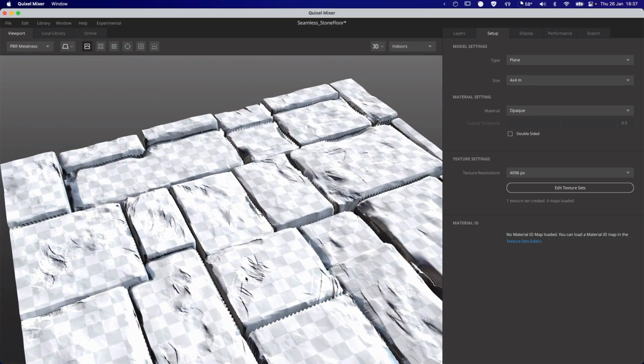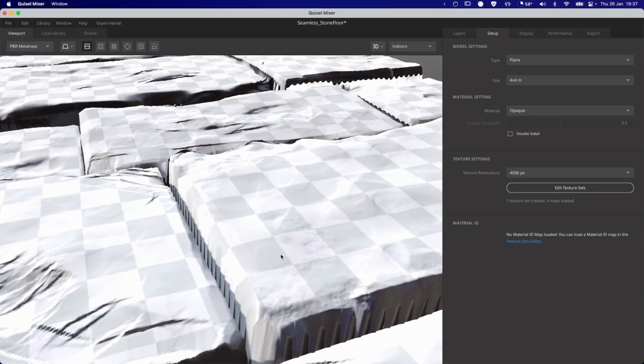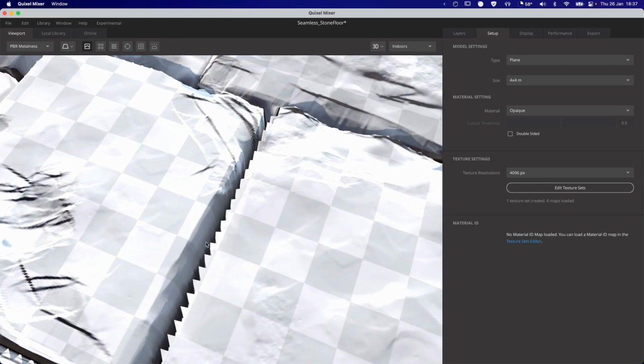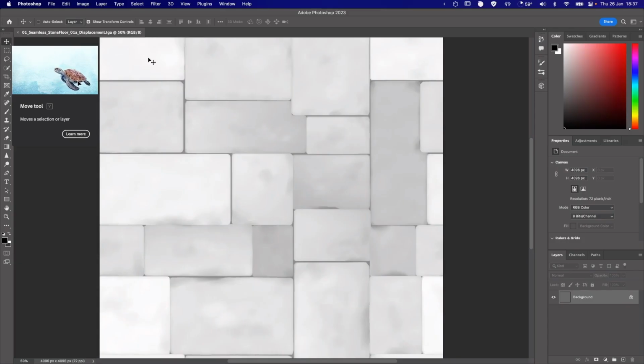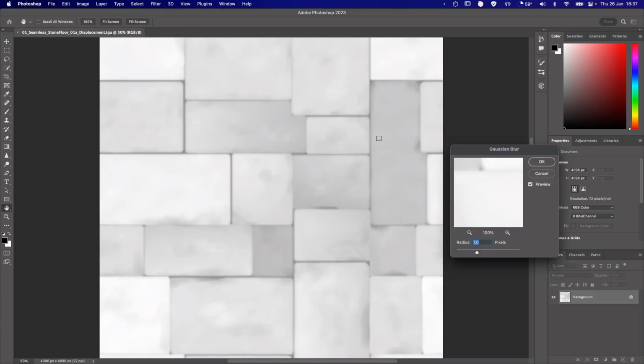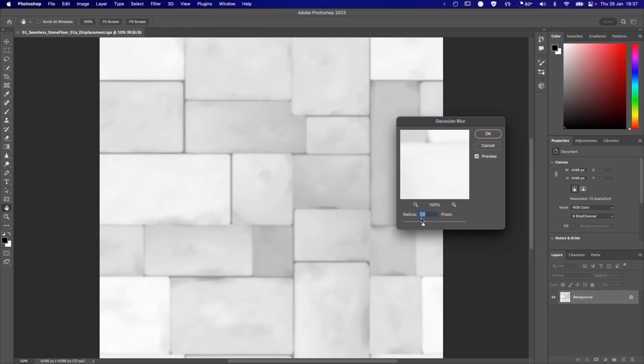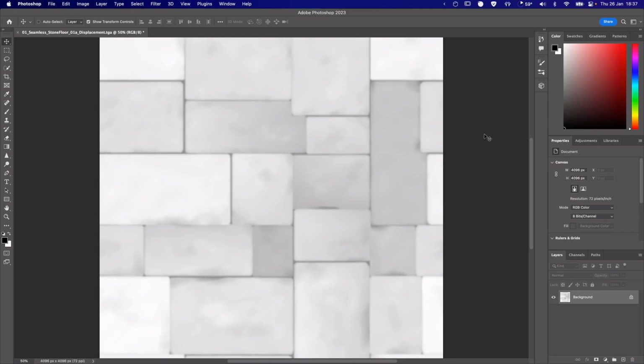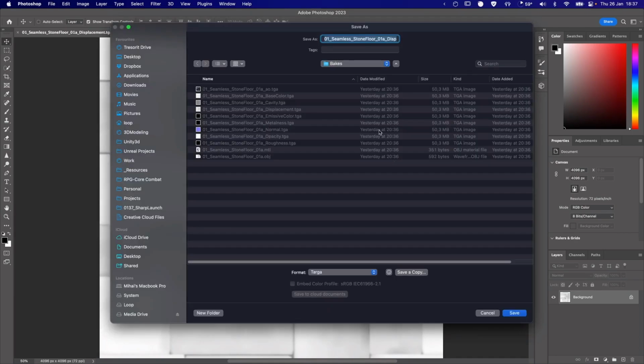We're gonna get these jagged edges because there's a harsh difference between black and white on our height map. And the way to fix that is opening it up in Photoshop, GIMP, or whatever photo editing program that you have access to, and just applying a small amount of Gaussian blur, and that will create a nicer looking fade between those harsh lines. In Photoshop, I used 7 pixels as the amount, and that seems to work perfectly. Save the file as a modified version of our original displacement map.